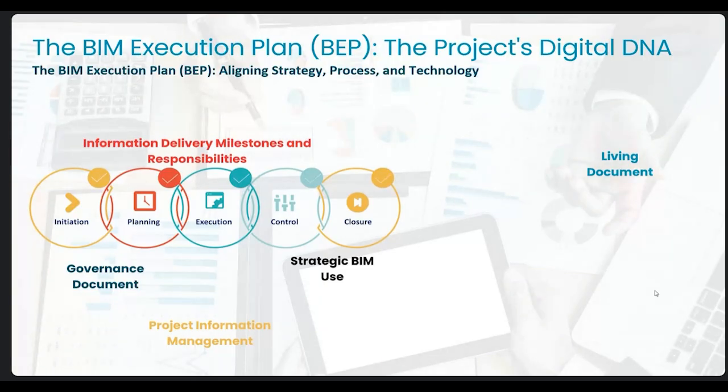It contains the entire strategy, how to start working on the project, which software needs to be used, which team is working on which project, the timeline, the milestones, the coordination meeting activity timeline, then the issue tracking, and multiple other things. Each and every phase we implement inside the BIM project is covered in the BIM execution plan.